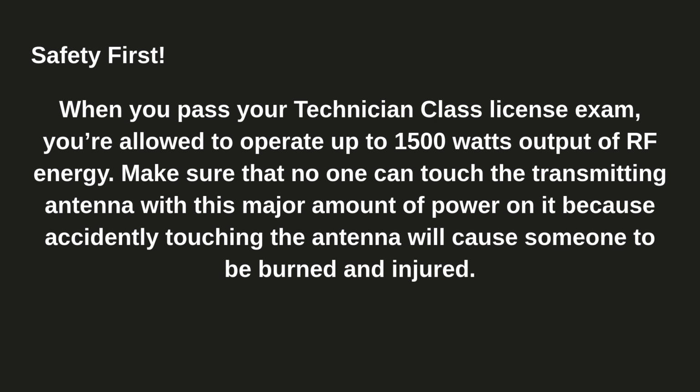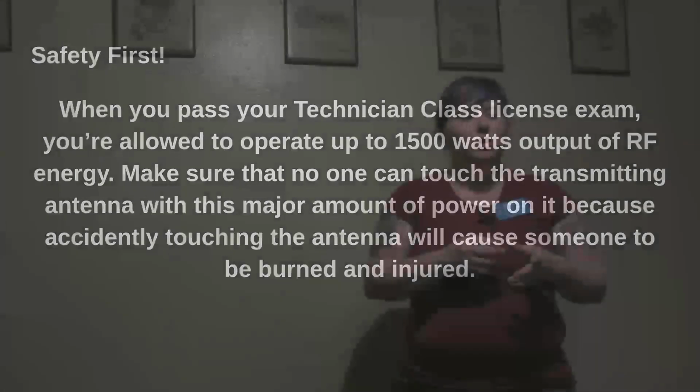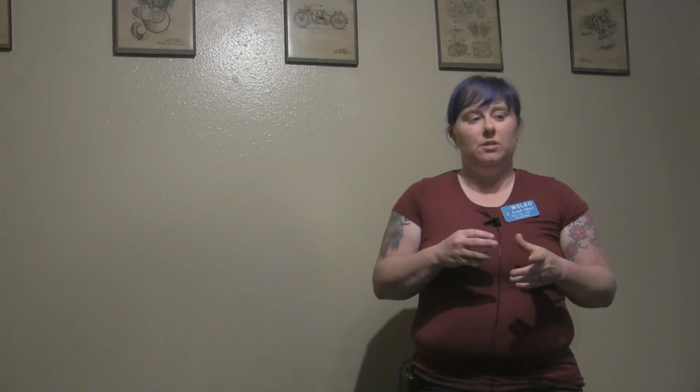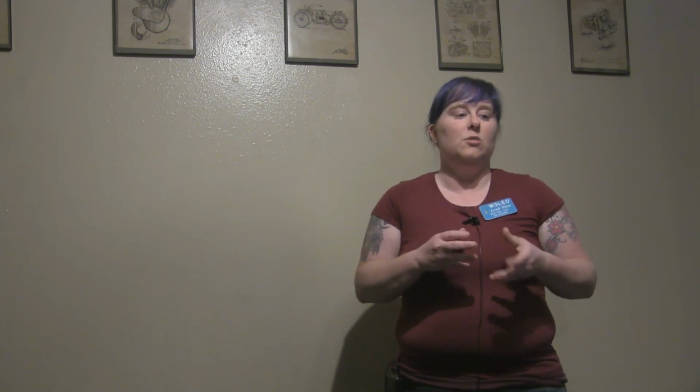Now, when you pass your technician license exam, you are allowed to operate up to 1,500 watts output of RF energy. So make sure that no one can touch the transmitting antenna with a major amount of power, because if you accidentally touch it, the antenna can cause someone to be burned or injured.